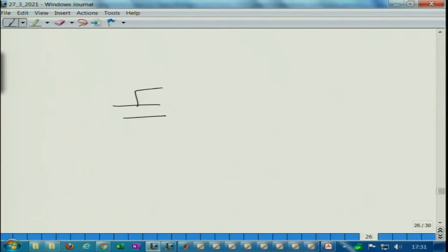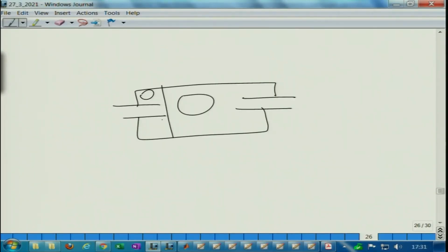We just had a glimpse of the 3D analysis, but there are lots of geometries there. As a final note for this lecture, the piston driven model can be used to analyze a lot of configurations, but for systems such as extended inlet and outlet systems, one necessarily has to consider modal coupling, at least between the annular cavity, that is, if you have a chamber like this, between this part and this part and this part, there is a fully coupled system, one must consider that.